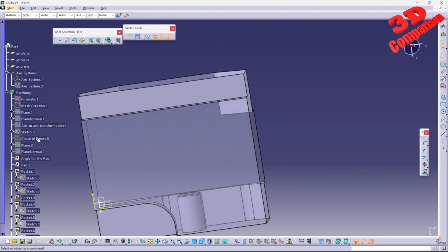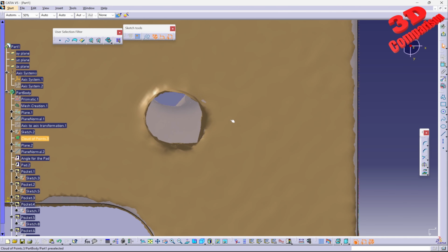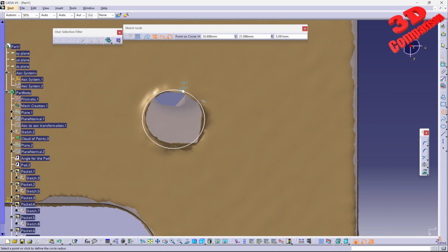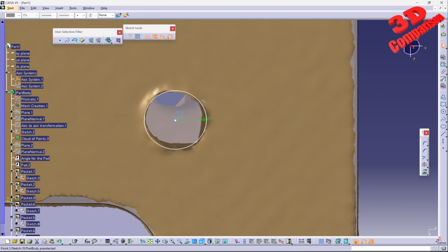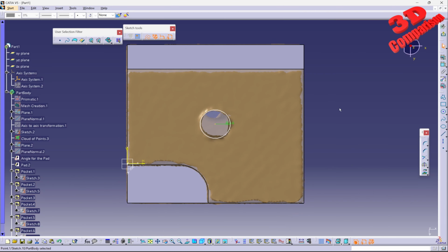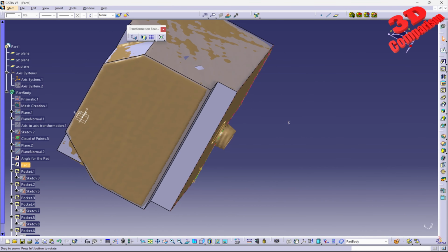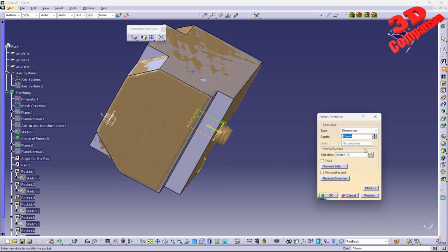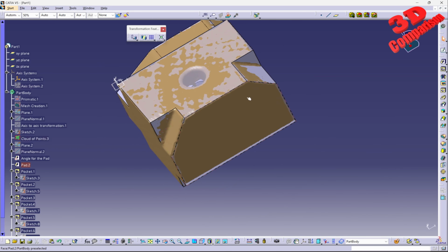For the bottom, this was mainly just used to have the element fixed, but we had a threaded hole over here on the bottom. So again, we can try to find the location of that. Usually we can do this manually by dragging the circle and see exactly where it would best fit. And afterwards I will just have this pocketed, for example 25 millimeters in this case.